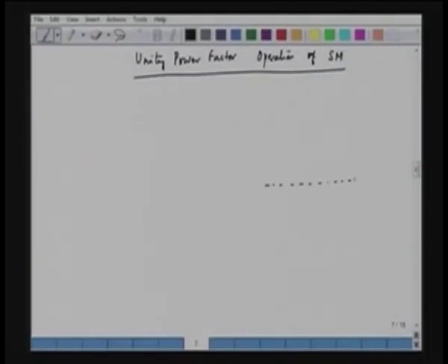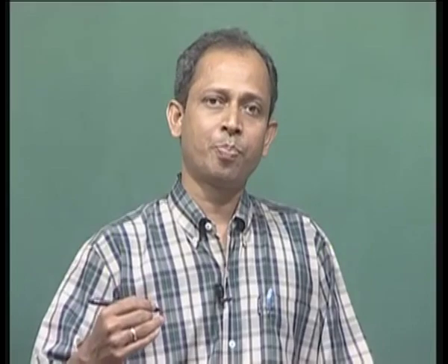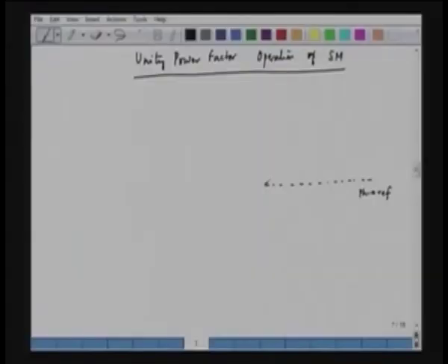So, what we have here is the phasor reference, and we can draw the phasor diagram. This is our phase A reference, the stationary phase A, and the rotor is rotating at a speed of omega r. So, we have the d axis of the rotor, and the angle which the rotor makes with the phasor reference is theta r, the rotor angle. And naturally we can say that the field current is along the d axis. So, if we show the field current phasor, this will be IF.